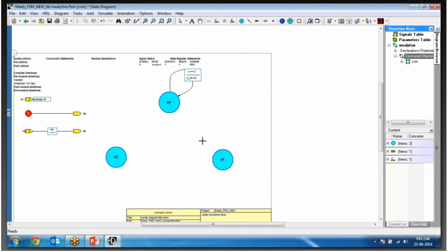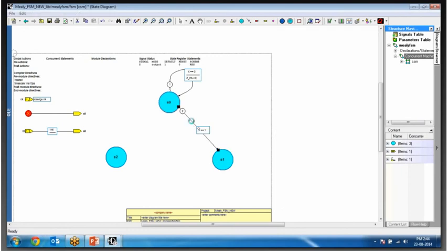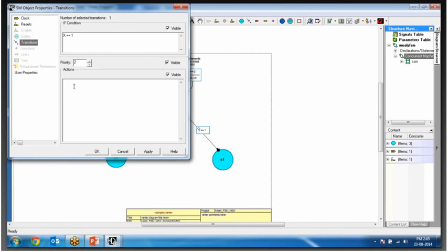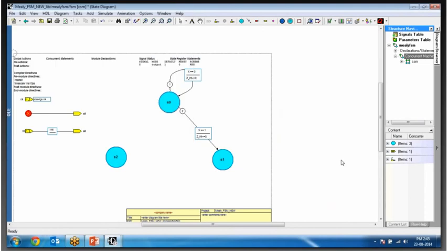Now I need a transition between state 0 and state 1, and I have to detect the pattern 101. For that, the first input will be 1, that is x equals 1. Select the arc, double click on it, and give z_int <= 0, because we have not yet found the complete pattern. Make sure you give the semicolon, else we are going to get an error during the simulation stage itself.